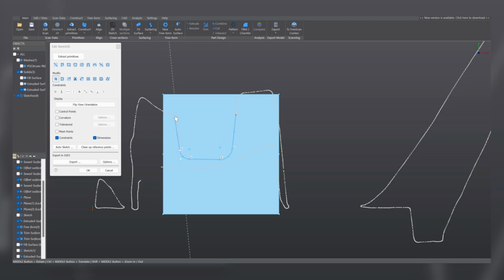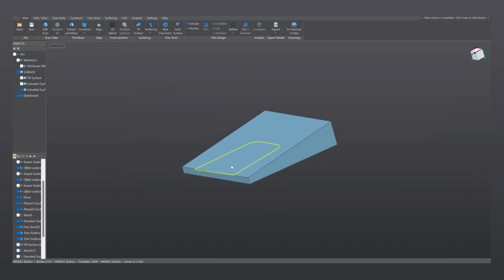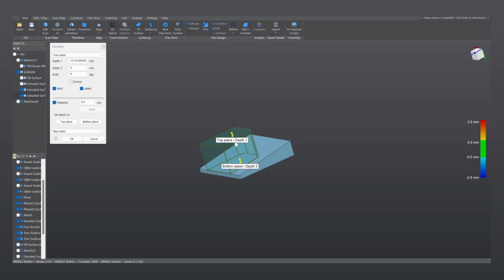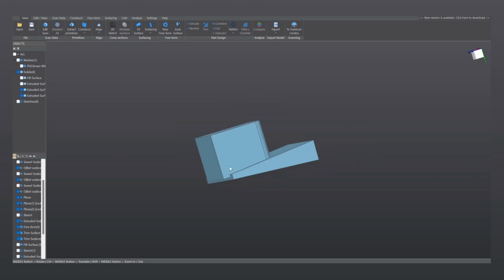And let's extend these lines beyond this body and close the sketch. All right, now we extrude this closed sketch till a certain height here, and here making sure that it extrudes until it's inside the other body. New solid is again selected, click on OK.